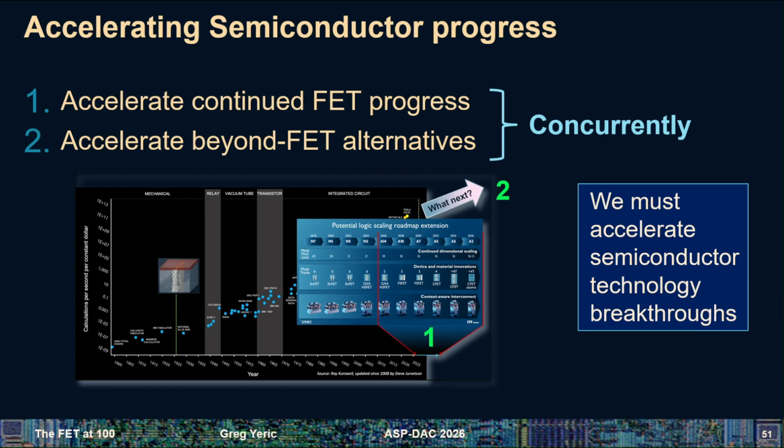So as an engineer, you say, okay, the mean of my simulation is this, and then I'm going to guard band up and down from that so that across any kind of process variation, my circuit will still work. So I simulate and make sure that my circuit is going to work at the slowest corner of the design of the transistor space, and the fastest corner. So we built in a bunch of margin.